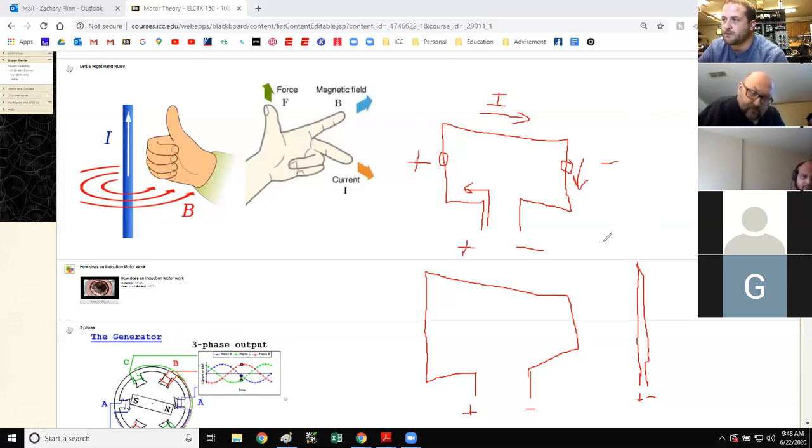Does that make sense? Yeah, it kind of artificially creates AC inside the motor. Yeah, that's perfect. That's exactly what it does. So you're applying direct current, but the commutator takes the current and applies it using those brushes that actually touch the stator to reverse the direction of current flow to keep that thing spinning.